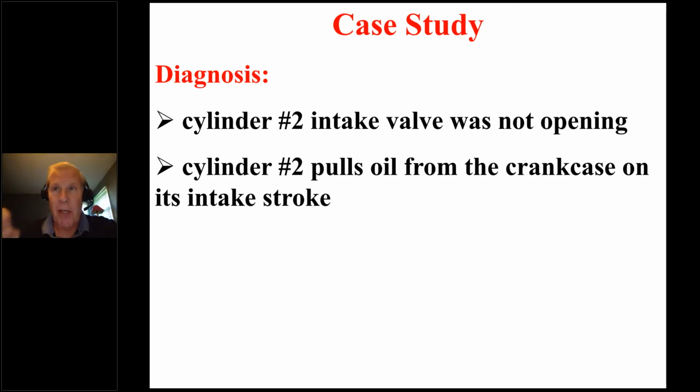However, if an exhaust valve is functioning, but the intake valve isn't functioning, every time that piston goes down and reaches that deep vacuum, it's going to start to evacuate the crankcase. So not only is it going to pull air out of the crankcase, it's going to pull oil out of the crankcase. And that's the reason for the oil burning. So hopefully connecting all the dots makes this work.